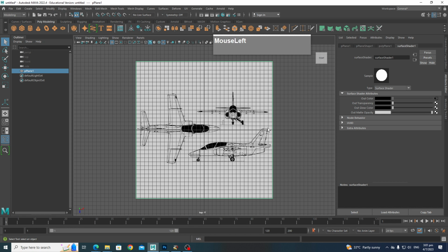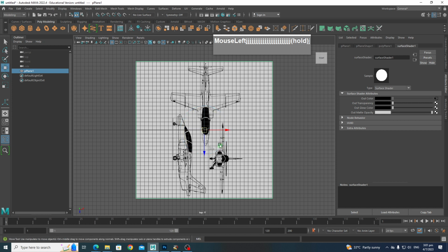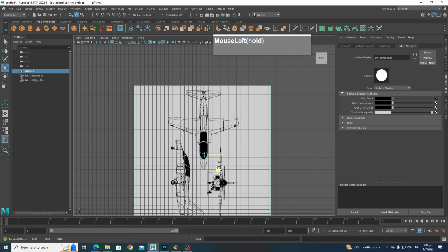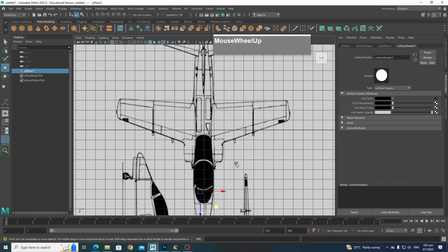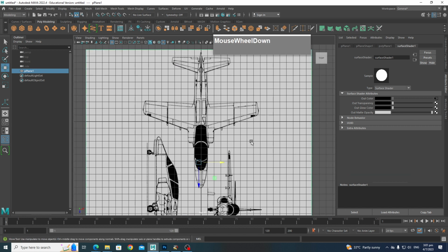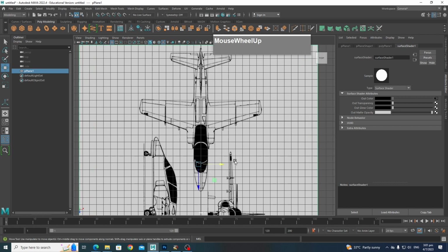So select the plane, press E to rotate, hold on to J, and then snap rotate it 90 degrees. Then press W, and then line the plane up right in the center, so that the thick line over here cuts right in the center, like so. Okay, so you can also choose to move the pivot point by pressing D and then just holding down the X and then have it snap to the center. Then press D again to hide it.